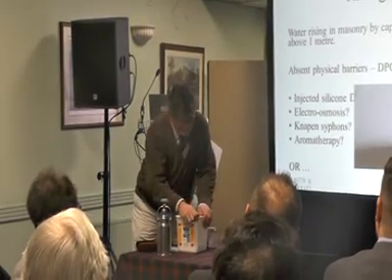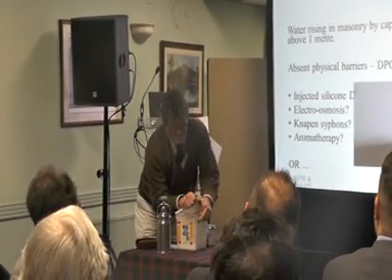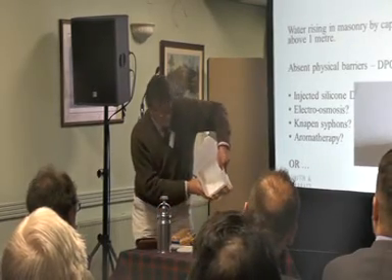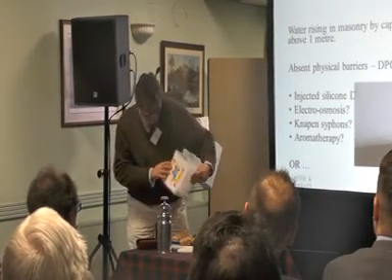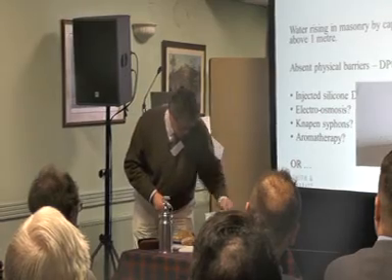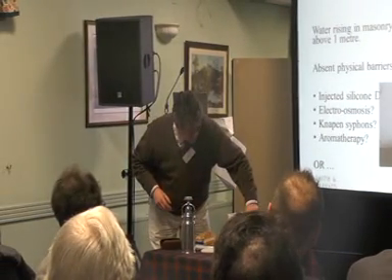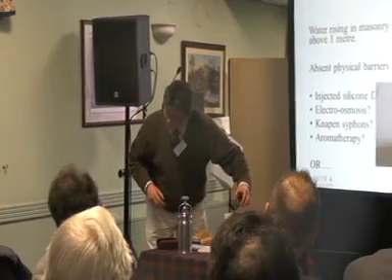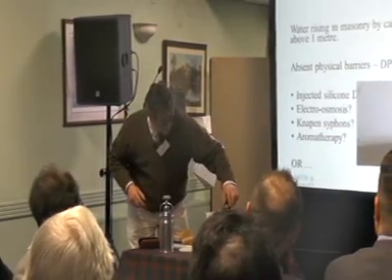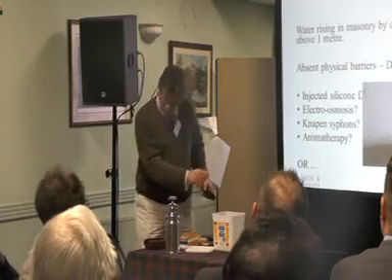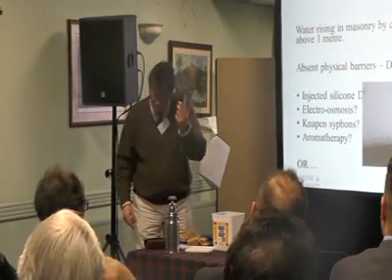Another one, absolutely classic. If you've got rising damp, it's going to bring salts, a mixture of salts, this is just normal table salt, out of the ground and into the wall. So when you put your damp meter in, that's just in a bit of table salt. It's confused. It's conducting electricity. That salt is dry, but it's telling me there's a problem.